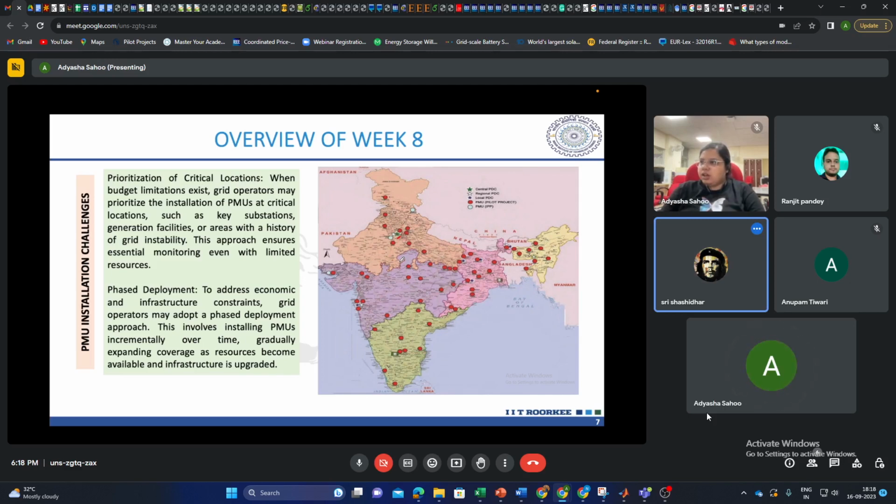See, what I get from you is that since they are the dispatch centers, they have the data for the generator dispatch PG, and they know the PDs also. So from that, they may compute the voltages and power flows in the lines. But that is on paper, in the software. What is happening in the real location? How will the NLDC get to know that the load has changed or some line has been cut off in real time? Also, when we are computing this in computer software, the line power flow limit or the line parameters R and X are also weather dependent parameters, and they are also changing. So those characteristics are very difficult to model.